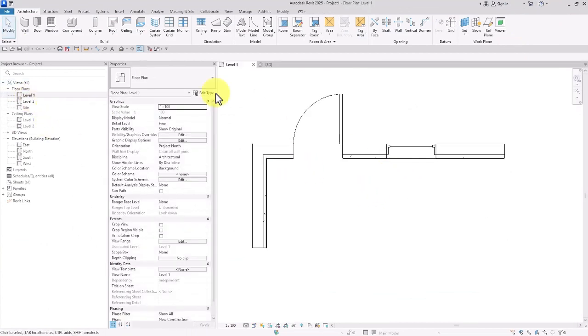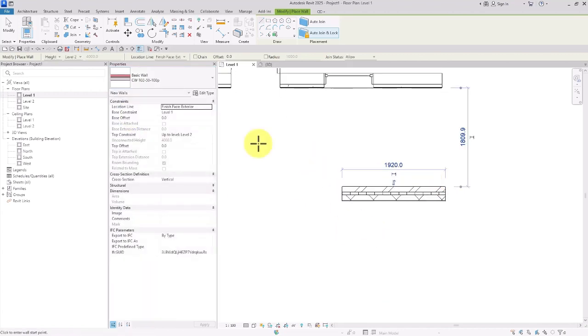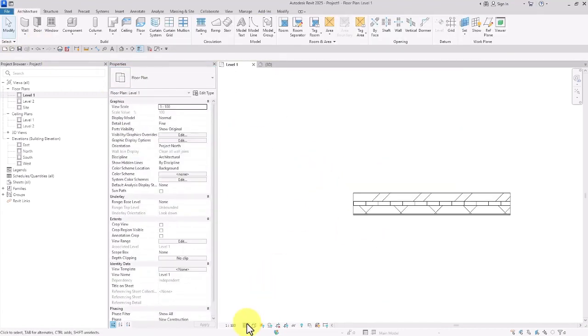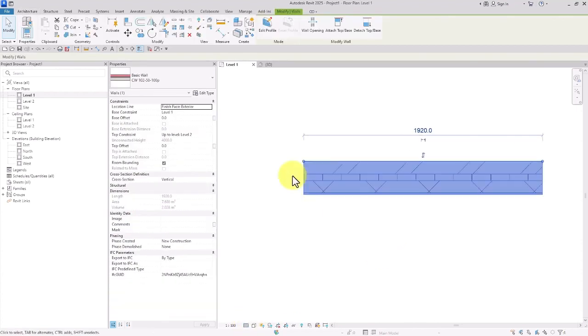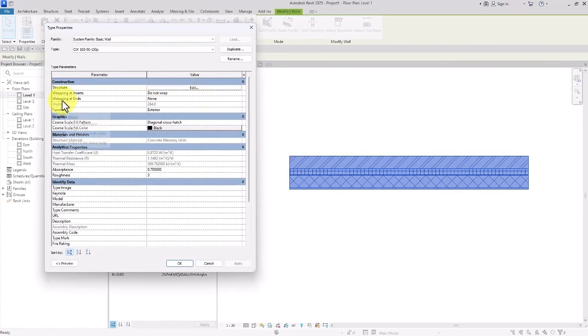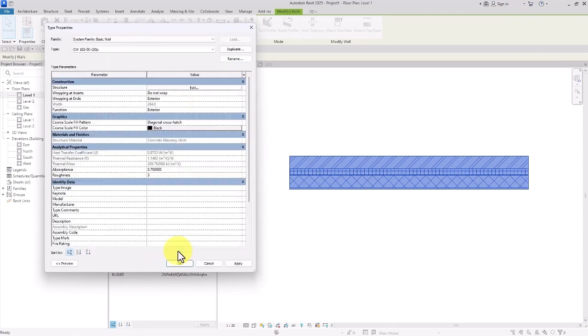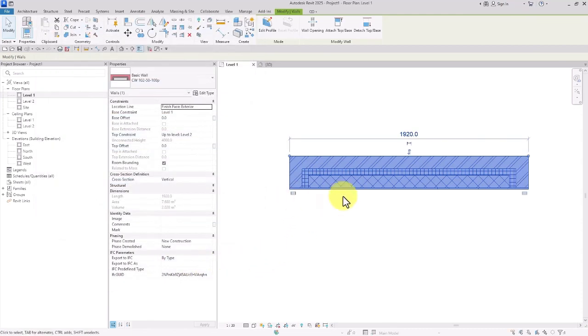First of all, the first thing that we need here is a wall with a finishing work set on it. For example, this wall. Now, when we select this wall, as you can see, no symbols would appear. If we want them to be displayed, we need to go ahead and from wrapping at ends, activate either exterior or interior option. Alright, now if I click on OK, the symbols would appear here, and now we are able to control the wrappings in our endpoints.